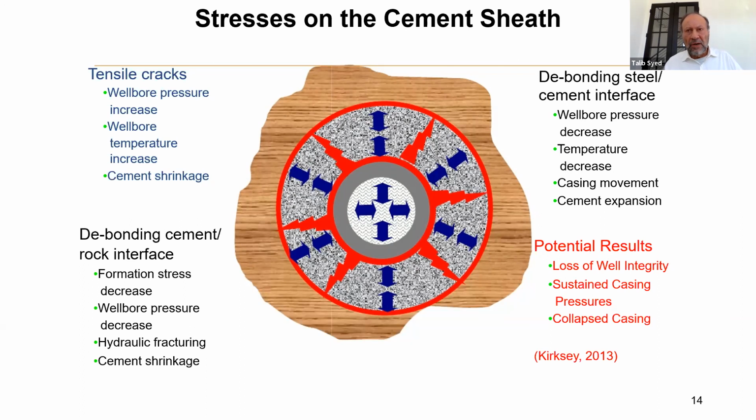So you know that you've got a problem on the backside, either due to influx of gas migration, a bad cement job, or some other problem that is causing the buildup and resulting in sustained casing pressure. So a lot of problems occur with well integrity in this area.